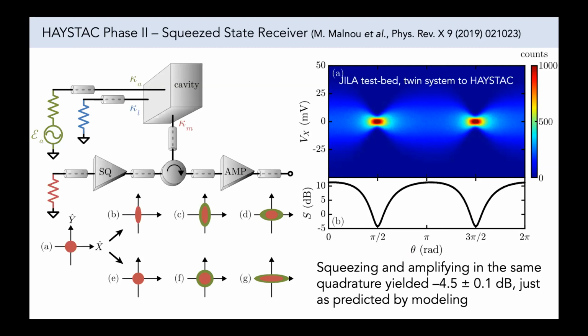And then what one has control over is in fact the Johnson noise, which in any configuration, as I've schematized here, is noise which is effectively reflected off the amplifier whenever one measures it.